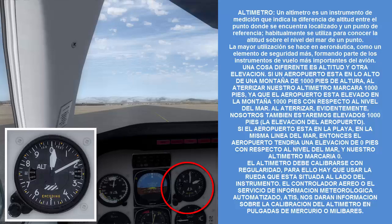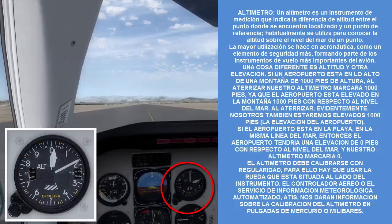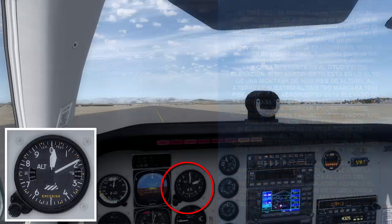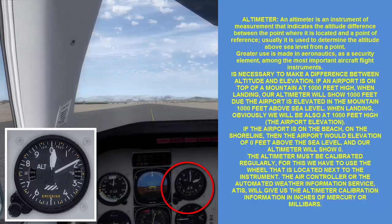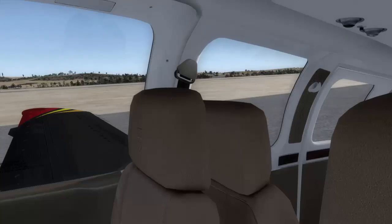Sorry, and we have there the altimeter. Okay, the altimeter, as I told you before, needs to be calibrated. So you have to calibrate the altimeter to make it work properly, and we will need that information, which will be provided by the air traffic controller, or when you tune the ATIS frequency, which is an automatic weather service provided by the airports, and it will give you the altimeter calibration to make it work nicely.